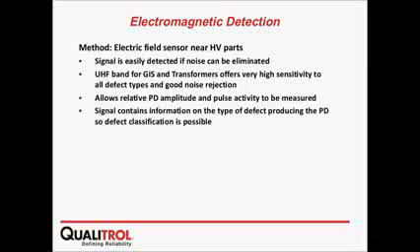So it's not only a matter of having an antenna internally or externally measuring the UHF signal from a PD, and not only a matter of storing that data. You need to have a smart system that can get that data and show it to the user, who sometimes doesn't have much experience with partial discharge. So it can classify what kind of failure or PD it is, if it's a void, a floating, a corona. So it can automatically identify and classify that PD.